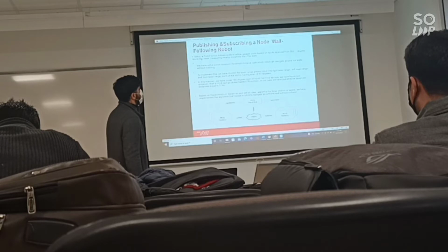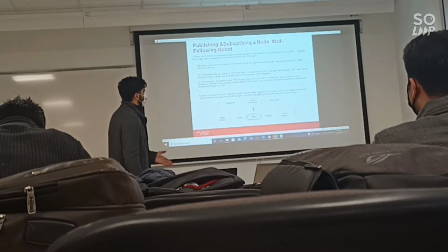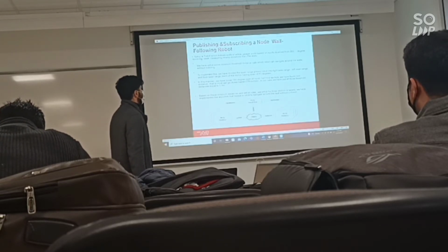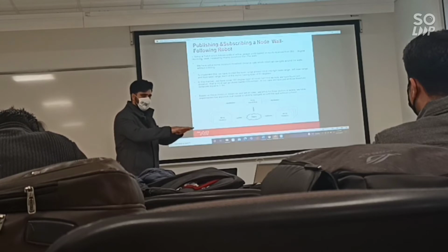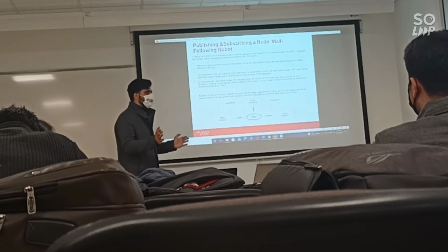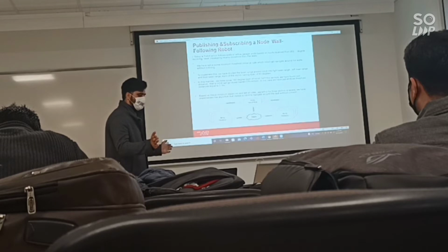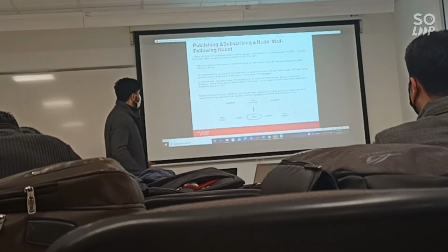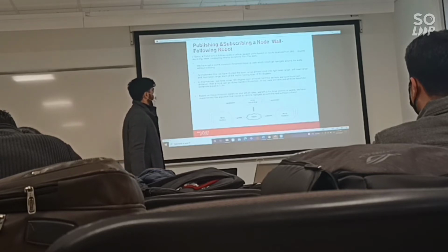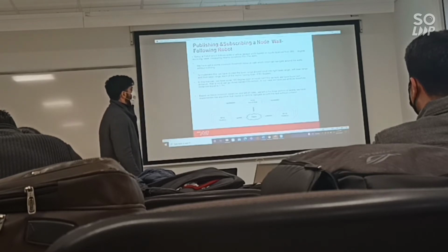To implement this, we have divided the laser range into right laser range, left laser range, and front laser range. Each sector has a span of 60 degrees. So if my robot is going forward, this is the section that is covered by the scattering lasers. I have focused on 180 degrees, broken down into 0 to 60, 60 to 120, and 120 to 180. Based on the minimum distance and the set of rules we set for the three sectors of the lasers, we have implemented the algorithm that makes the robot navigate around the walls without collision.